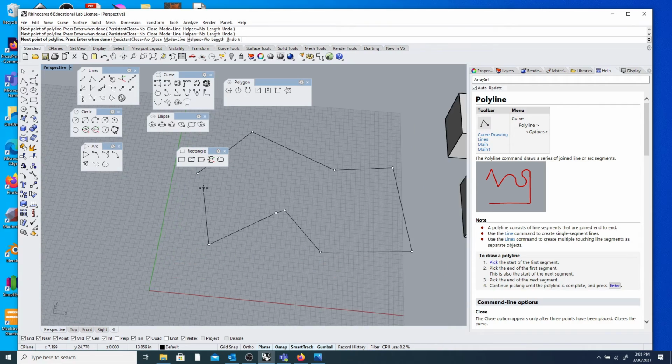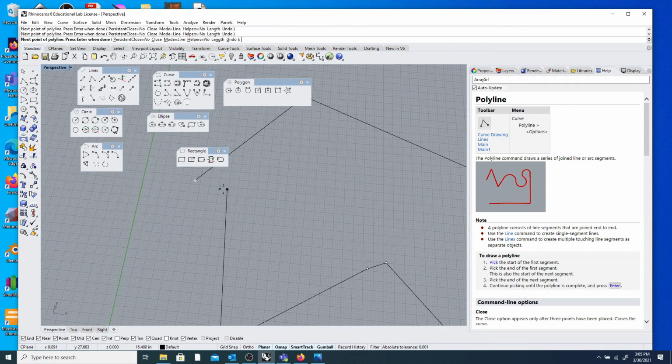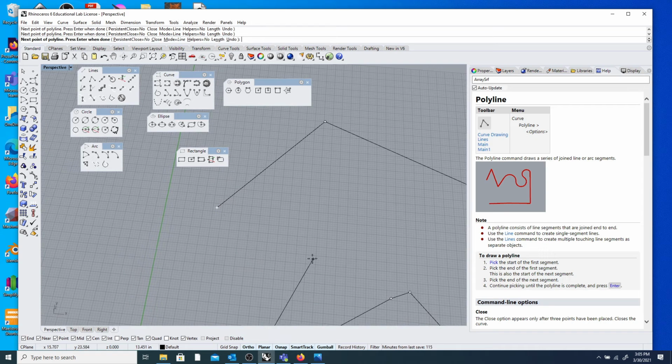And then to close this, so to close geometry with curves, it has to be to a snap. They have to snap closed. Otherwise, it will not be a closed curve, and that could lead to lots of issues down the road.